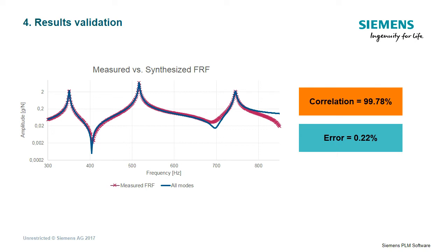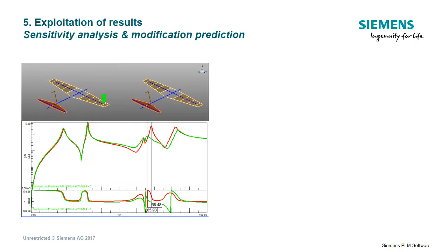In many modal analysis solutions, several validation tools are available. For example, how complex a mode is, or how sensitive a mode is to mass variation. This last parameter can be used to understand if the selected mode is a physical one, or rather just a numerical artifact with no physical meaning, merely there to reduce the error. Once we have identified and validated the modal model, the actual modal analysis itself can be considered as concluded.